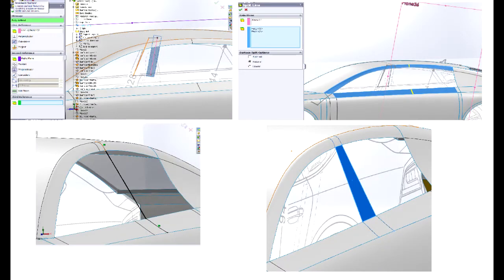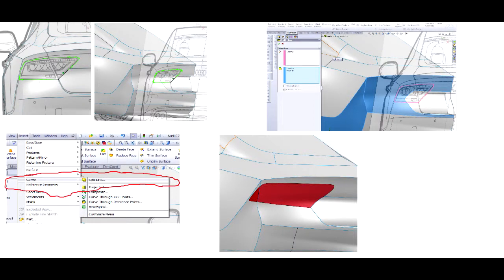Here are two examples for the Split Line tool. You can see that I was able to use the previous sketch to add a plane and split the surfaces. The splits are then used as references for the splines, which helped create a new boundary surface off existing surfaces.